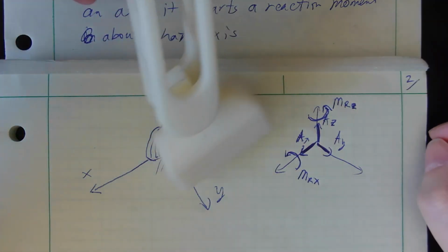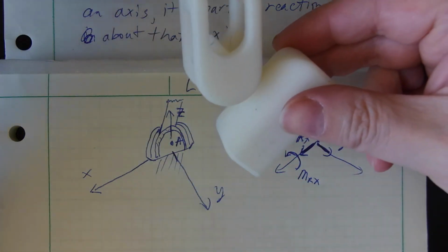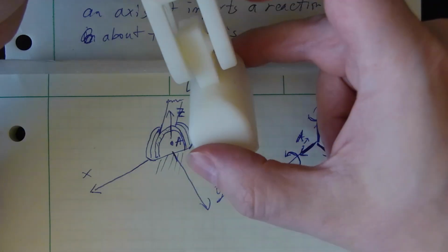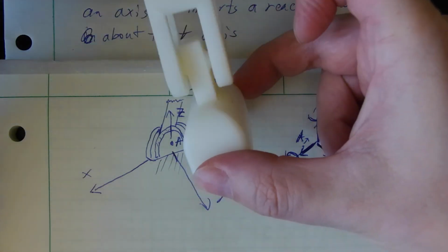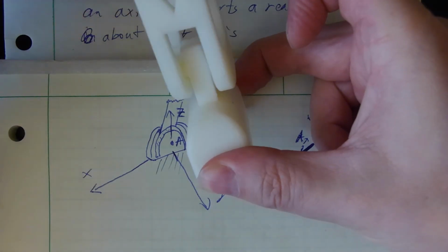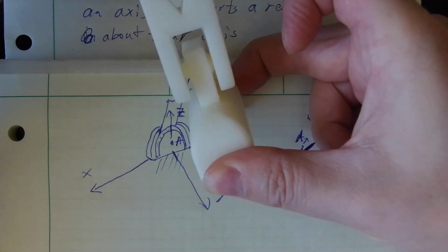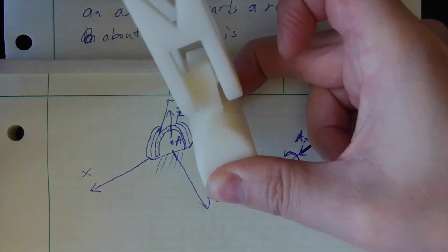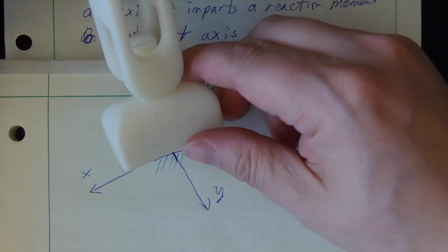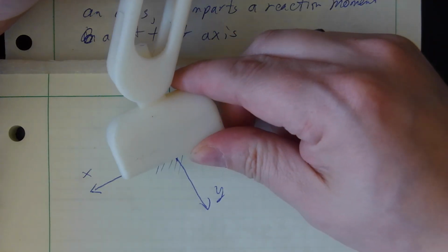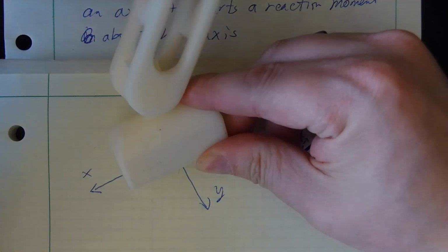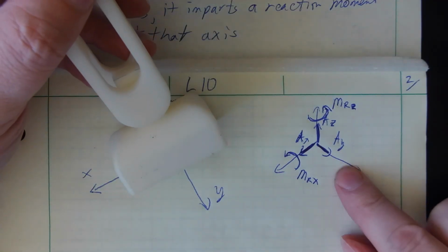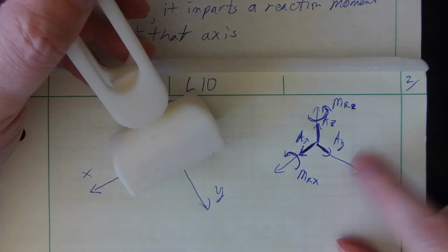Hopefully this shows up. So, a little better. I should have just set this next to me and drawn it like this. But you see the pin is in here, right? It can rotate about this pin, but there's some slack in there since it's printed. So I can't rotate it about the vertical axis. So if I put this in the direction of what I've drawn there, notice that because the pin is in this y direction, I can rotate it about the y-axis. So there's no moment here in the y direction stopping the rotation.